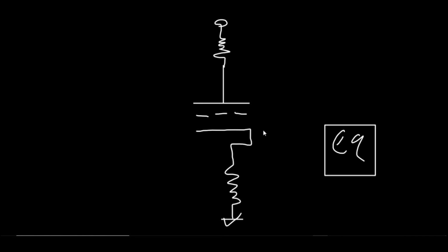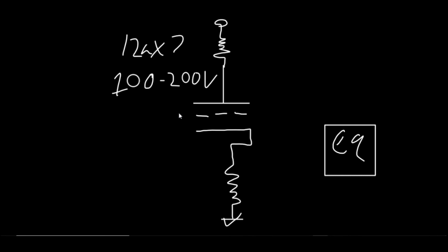Now, what makes a vacuum tube more friendly? Well, it's because vacuum tubes, like a 12AX7, which this could very well be, will run anywhere between 100 to 200 volts. That gives us a lot more headroom to run this 17.5 volt peak to peak voltage.